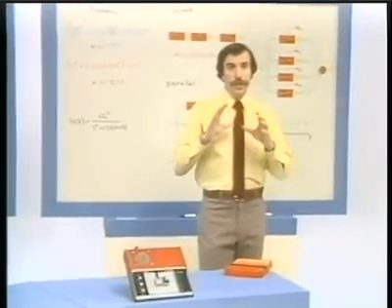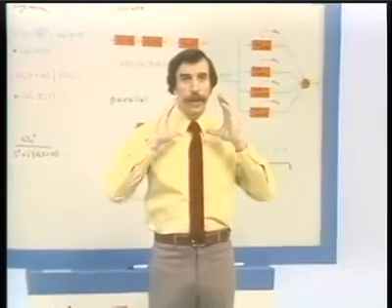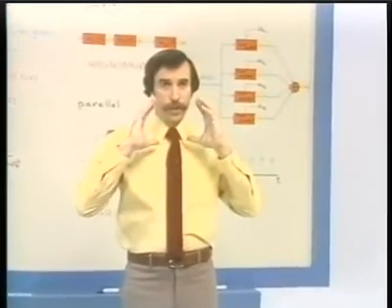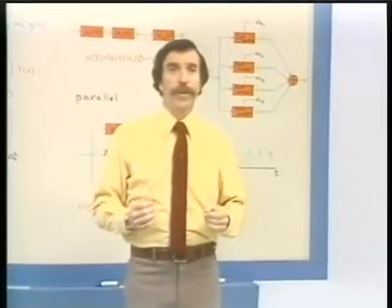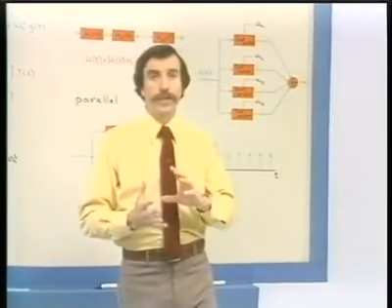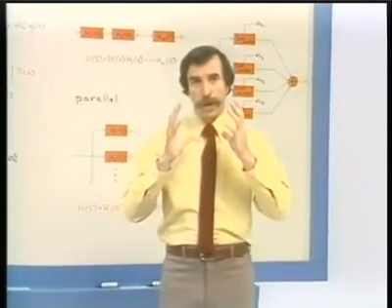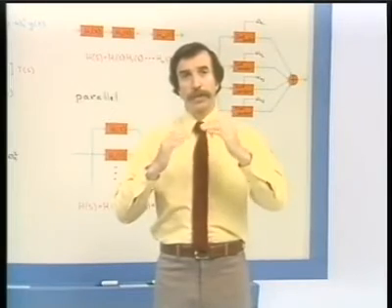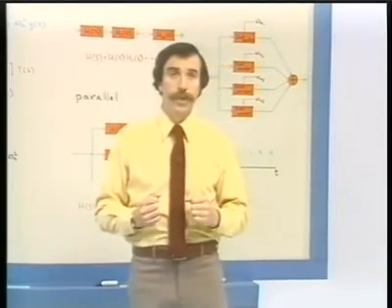In speech synthesis, what we're trying to represent or implement is something that corresponds to the vocal tract. The vocal tract is characterized by a set of resonances, and we can think of representing each of those resonances by a second-order system, and then the higher-order system corresponding to the vocal tract is built by, in this case, a parallel combination of those second-order systems.